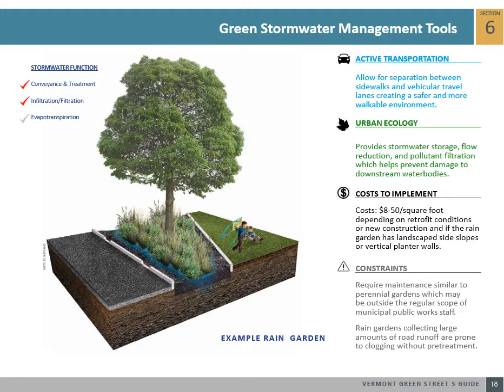Stormwater curb extensions, or curb bump outs, are landscaped areas that extend into the street and capture stormwater runoff. Conventional curb extensions, also known as bulb outs, chokers, and chicanes, are commonly used to increase pedestrian safety and help traffic calming. A stormwater curb extension shares these same elements, adding the benefit of stormwater management by allowing water to flow into the space for treatment through soil media and vegetation. This landscape space can be designed with the physical characteristics of vegetated swales, planters, or rain gardens, depending on the availability of space and specific site conditions.